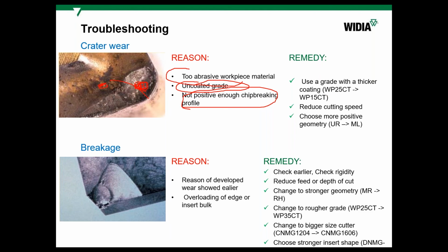keep the chip from contacting the flat, negative part of the chip breaker, so the chip will go inside the chip breaker and go out. There will not be bigger resistance to friction between the workpiece material and the cutting tool material.